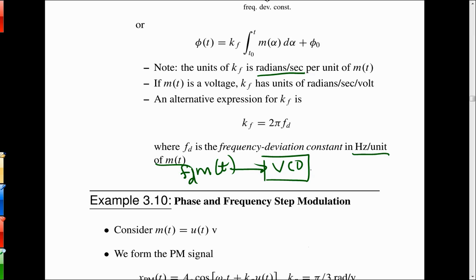So frequency and phase modulation both store the message inside the carrier signal's phase? They put it inside the argument of the cosine, yes. And what's cool about that is the envelope of the signal is constant. It does not fluctuate. It's just what's inside that deviates back and forth, so it has what's called a constant envelope. Now that gives it some very nice properties.